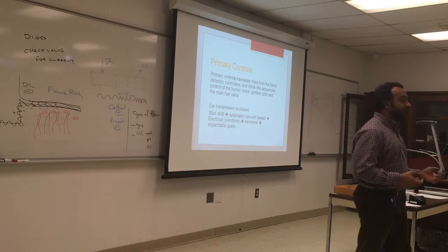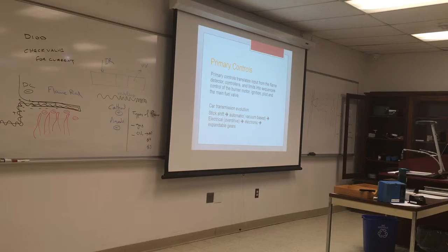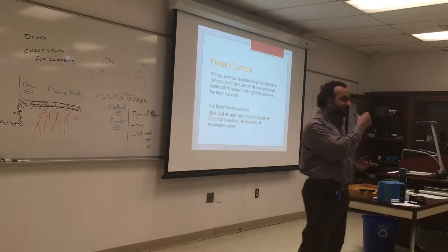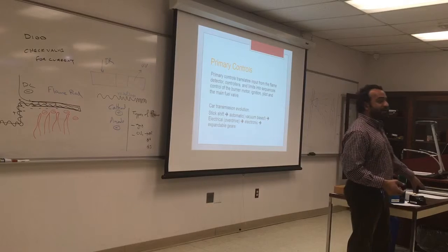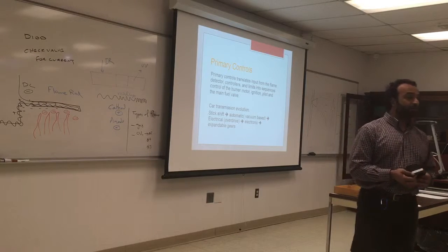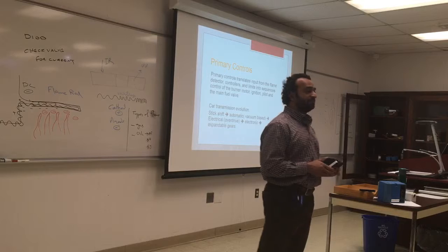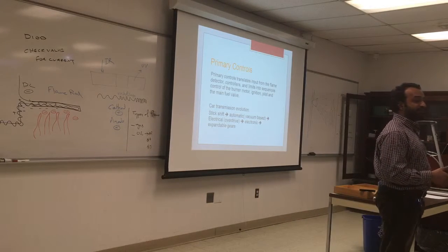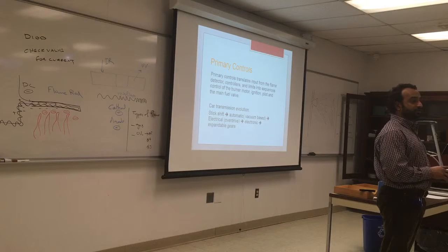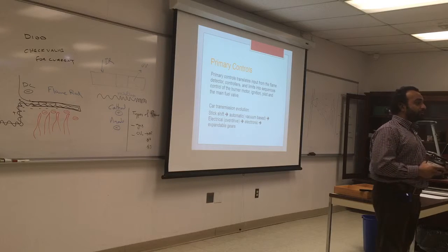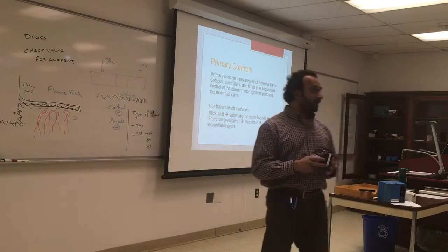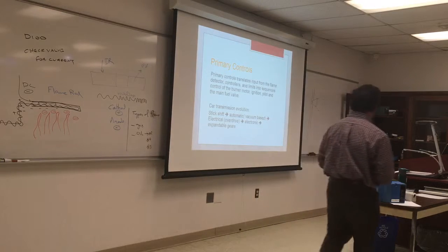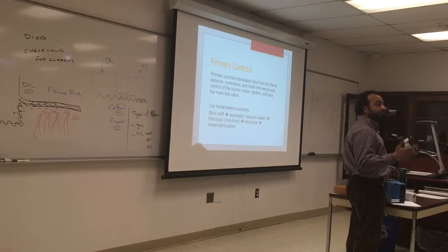At some point, it's highly unlikely, but it does happen, that the primary control is faulty and is not working. That happened with me and Eric last week, on Monday, where we tried every possible solution with the primary control, and we found out that the primary control shuts down on safety in 15 seconds, even though the cad cell is okay, even though the ignition is okay, there's flame, there's oil, it just shuts off. After we exhausted all the options, we changed the primary control, and it worked just fine. So you have to go and check the primary and check all the possible answers before you condemn the primary control. Something could have been a wind rock and the relay inside.